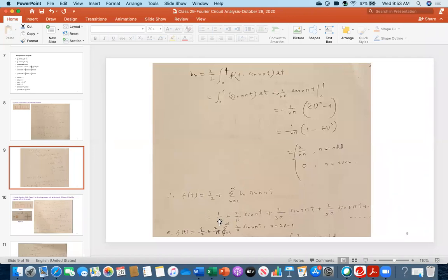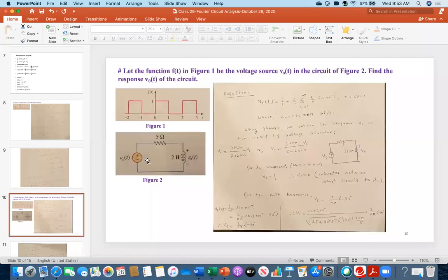This result has a DC term and then a sine term. Unless it is a sine and cosine term, we cannot apply any phasor technique. Everybody remember, phasor algebra technique was applicable only for sinusoidal functions. Or you have learned in DC circuits, if there is a DC voltage source, then the inductor will be a short circuit and the capacitor will be an open circuit. So unless it is a DC signal or a sinusoidal signal, you cannot apply it easily.